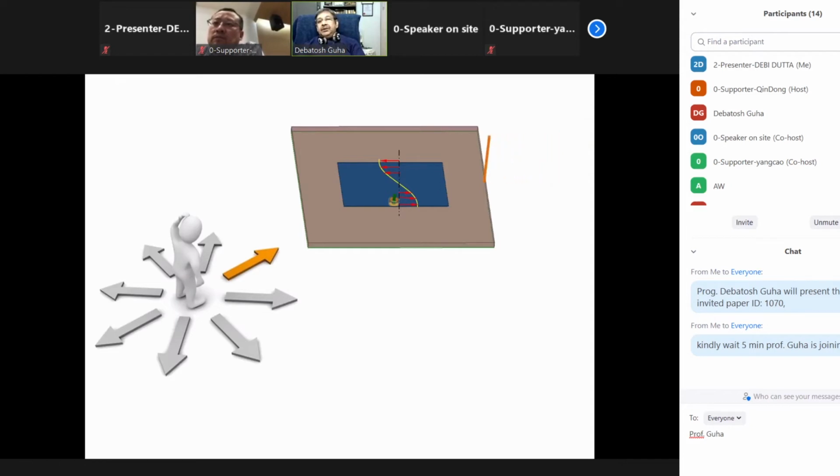We are just going to introduce one single pole on top of this patch. The length is lambda by 4. The physics of lambda by 4 is not very complicated, but you will see the results very interesting. You consider any lambda by 4, that is quarter wavelength current path, you will see its input impedance is equal to 0. It has to be 0. So only this simple principle is being used. Now you see.